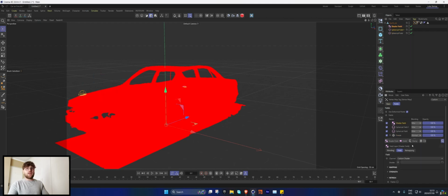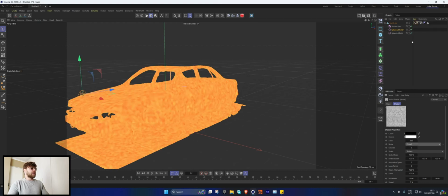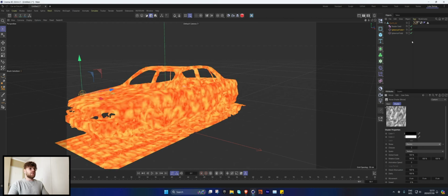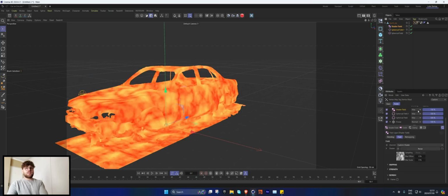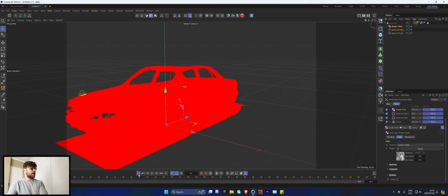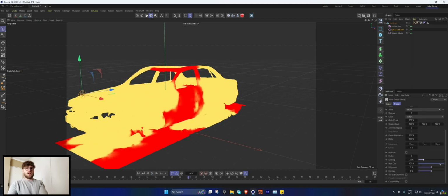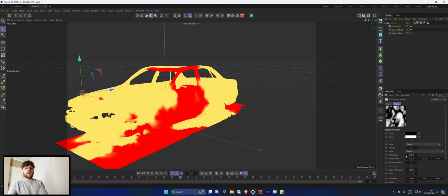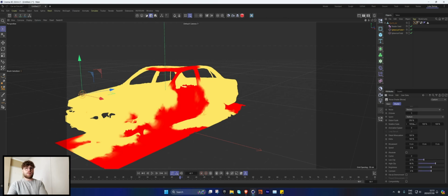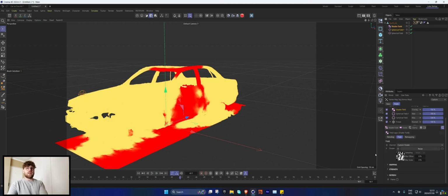Let's go over here and add a shader field. Let's change this to noise and select a noise type, something like that, that looks good. Let's make the size 250 and set this to overlay. Now let's press play again. Looks good. I just want to amp this a bit so that we have a little bit more broken space. Maybe make this 150. Actually, I think that should be fine.